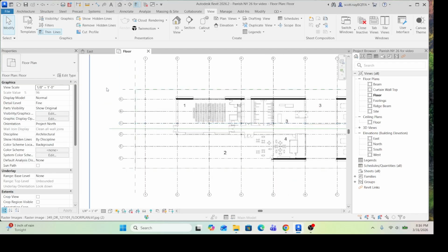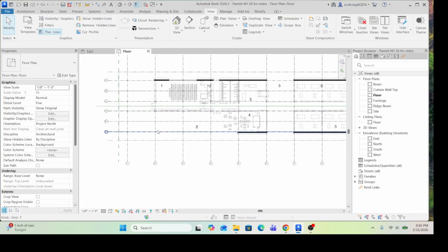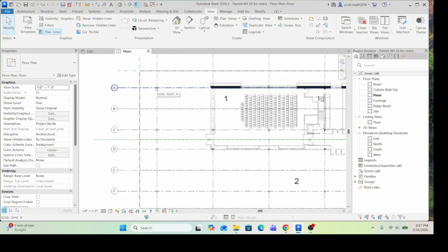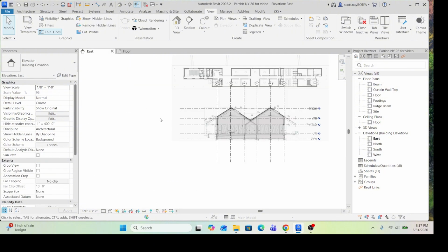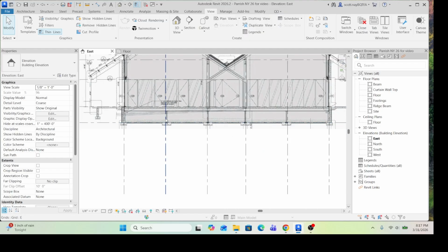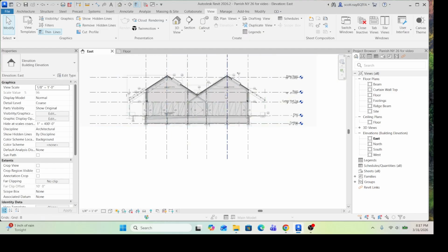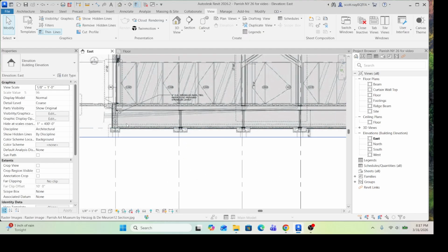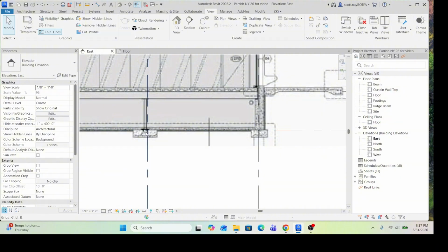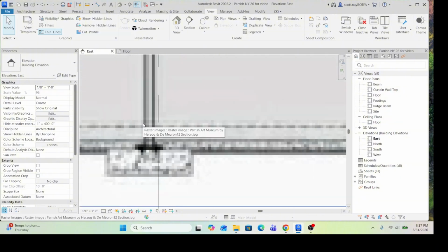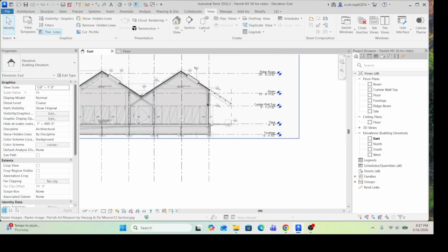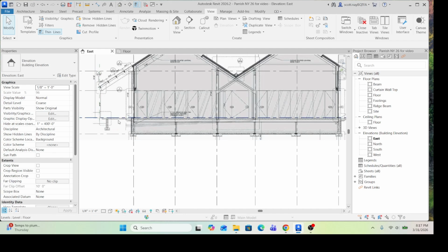And now, because we have grid systems in place, we can start with some columns, and we'll do the ones that are underneath. If we look at our elevation, we are going to have them everywhere. So we might not have steel beams in here, but underneath the ground, we're definitely going to have concrete columns, either isolated or a wall, and then footings. So let's start with the actual wall. And remember, we have an overhang here with more footings.